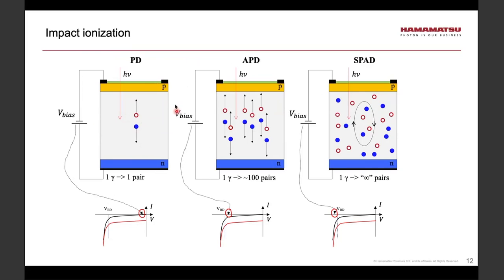So it's highly exaggerated size of the depletion region. In the depletion region, there is electric field which separates these two charge carriers. Therefore, the electron drifts towards the n region and the hole drifts towards the p region. And you can think of electron then recombining with the hole, producing a photocurrent.